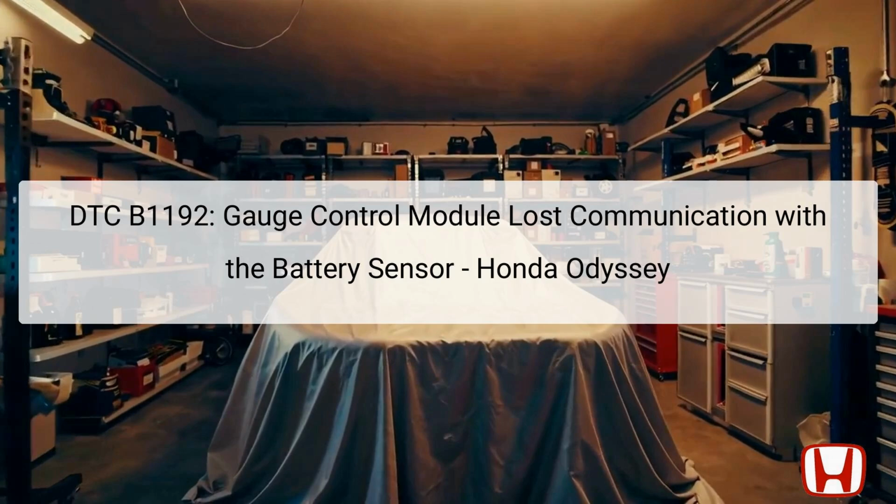The DTC B1192 error code indicates that there is a loss of communication between the Gauge Control Module, GCM, and the Battery Management System, BMS sensor over the UART, Universal Asynchronous Receiver Transmitter line in Honda Odyssey models from 2011 to 2017. The Gauge Control Module plays a critical role in monitoring and displaying vital information about vehicle systems, while the battery sensor measures battery health and communicates vital information about battery status.